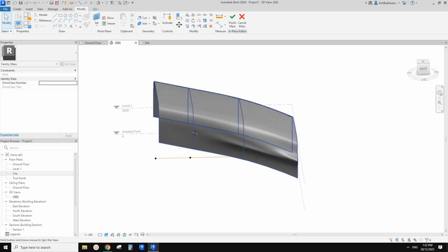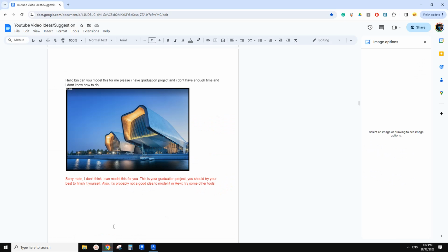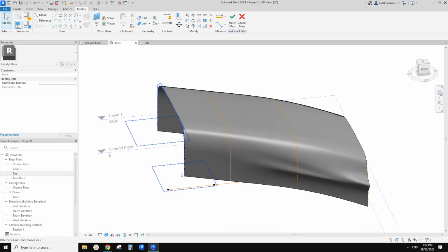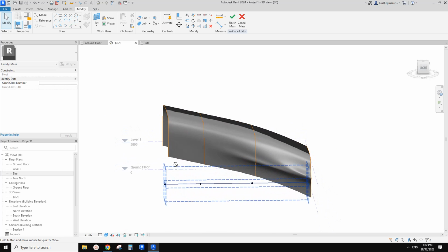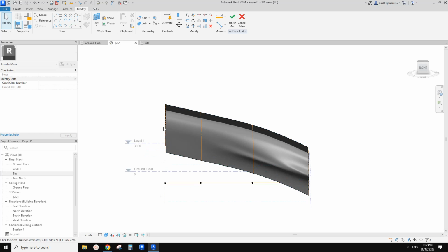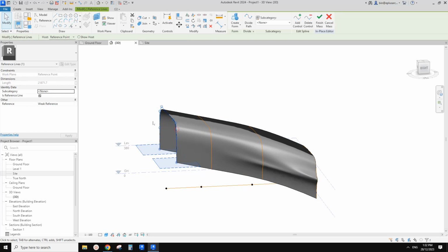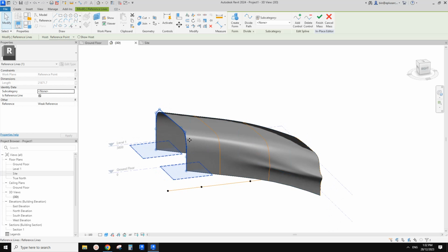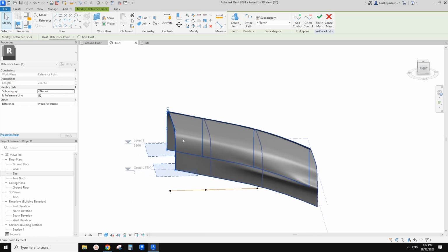And I think you might need to, you can see there's a little bit, it's not perfectly flat. What you can do is, because currently we have this profile as a spline on this point, if we rotate to this side, it will be perfectly flat. Okay, because spline will be two-dimensional, so it's always in one plane, not like spline through points, right?